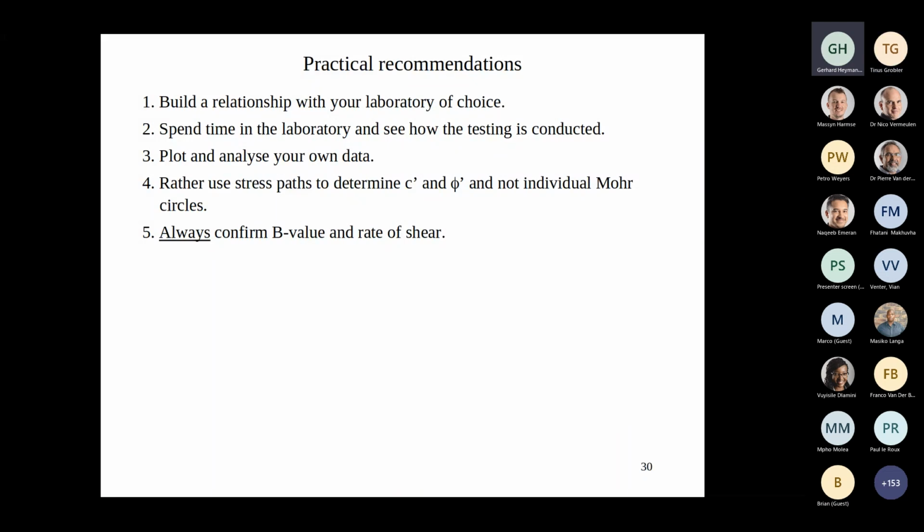So in my experience, I would tend to avoid using any of the data beyond development of shear banding. And in most cases, the information up to shear banding is sufficient for whatever the engineer is after. So that's the short answer: there are ways to do that area correction, but I'm not convinced that it's reliable. And I would actually only use the data up to the point of shear banding.